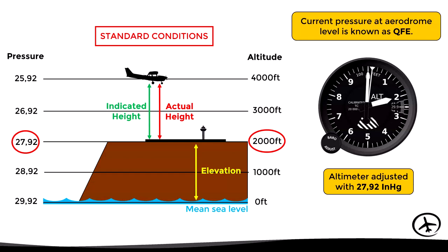Now, as with the QNH, if the pressure conditions are different from the standard, the QFE for a certain airport will vary. Therefore, it is important to obtain updated QFE information if we want to use heights instead of altitudes in our altimeter.